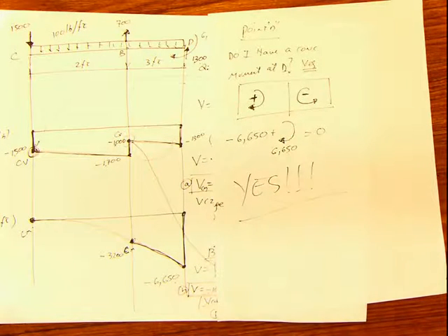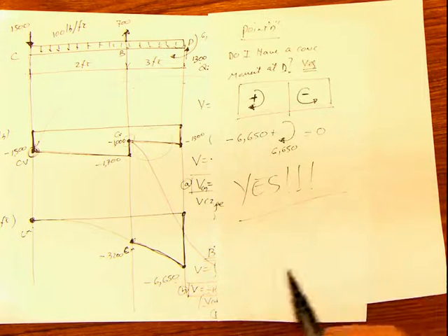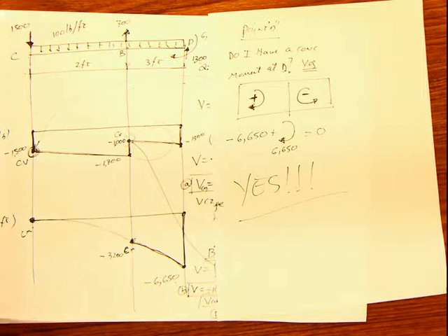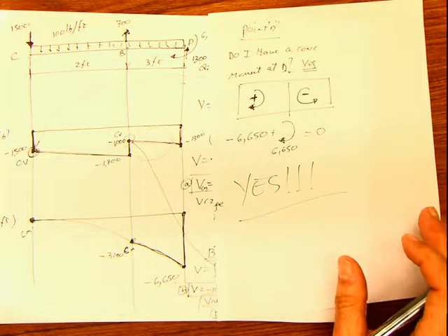Well, this problem has two new things. One is that we have to separate the beam into parts in order to solve each one of the parts, and the second is this one. Every time you have a concentrated moment in the beam, whatever is counterclockwise is a positive jump, and whatever is clockwise is a negative jump. For concentrated moment, this is the convention. Learn this, please. Now, if you want, we can also solve this with the method of the areas, or at least verify it.